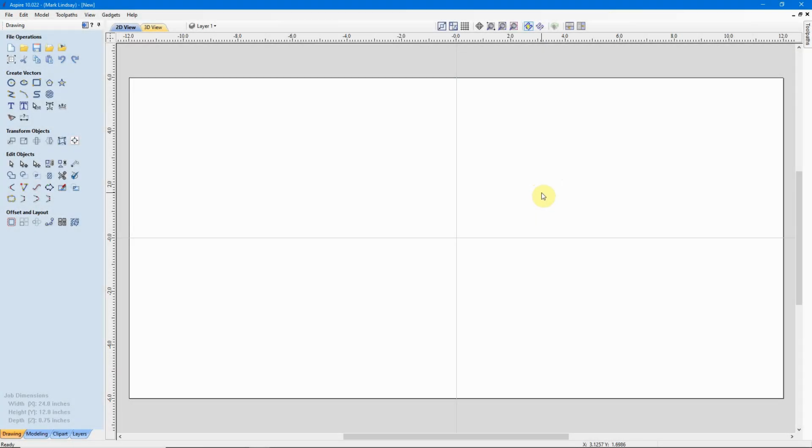Hey y'all! In this video, we're gonna step way back to the basics, and I'm gonna cover a topic that I should have covered a long time ago, and that is vector creation and placement. We're going to get into placing vectors in a specific location on our material, and that'll include rectangles, circles, ovals, polylines, and I'll even play with a 3D model a little bit.